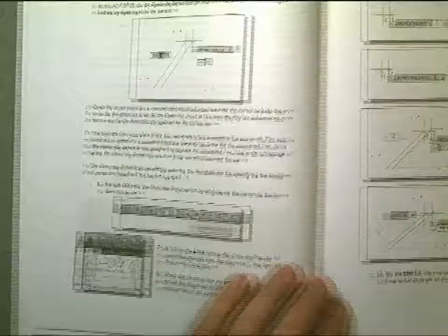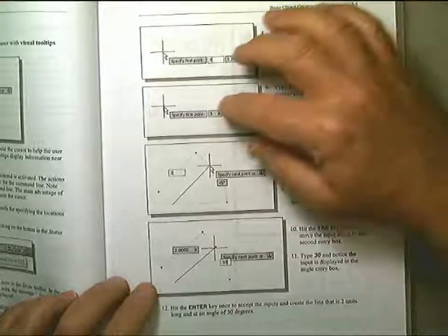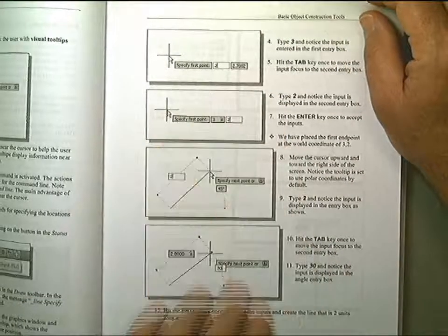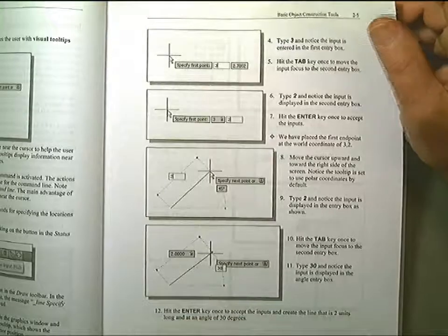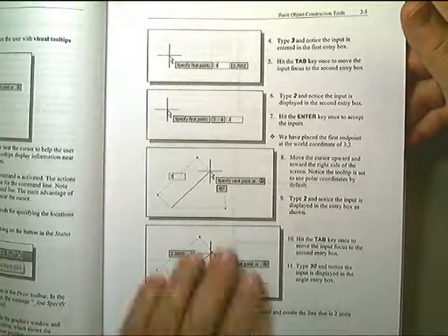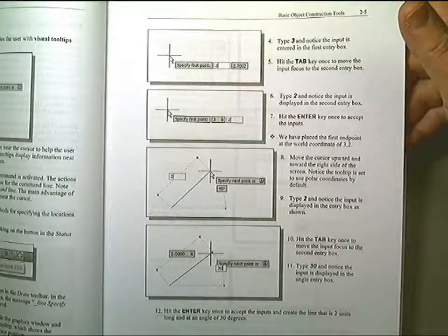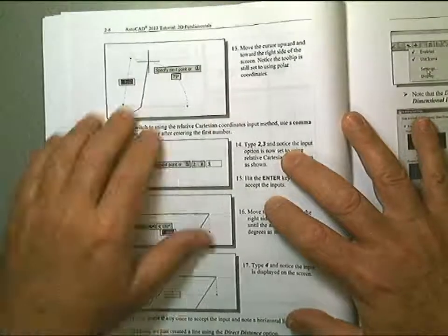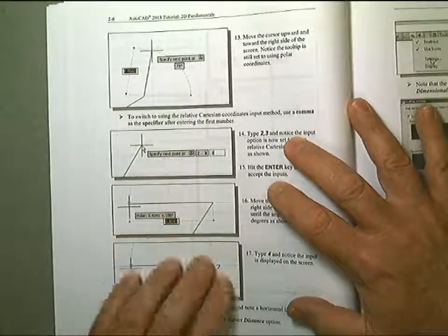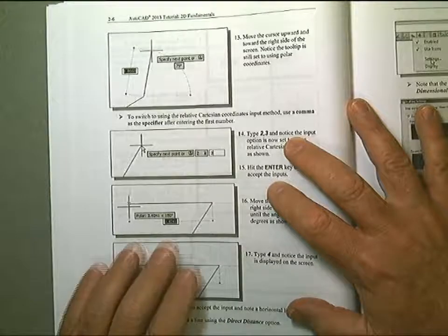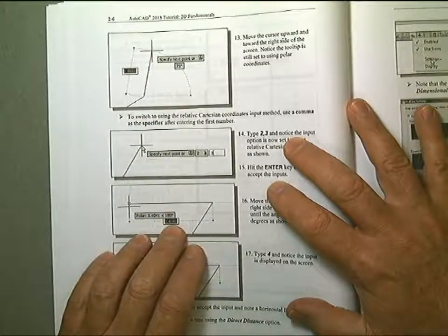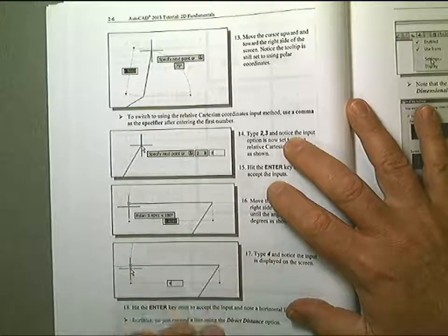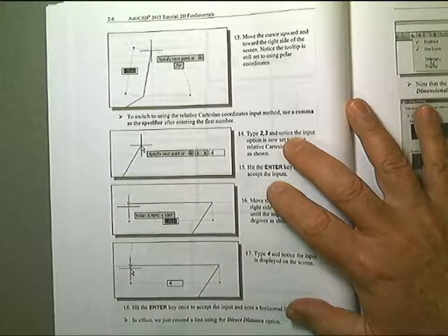You begin by practicing using it, drawing with the line command. Now, you may already have started doing this, perhaps even noticing it in the previous chapter tutorials. So you practice using it. Be sure and step through each one of these as it allows you to practice with doing just standard points, X and Y points, or by entering a distance and an angle.